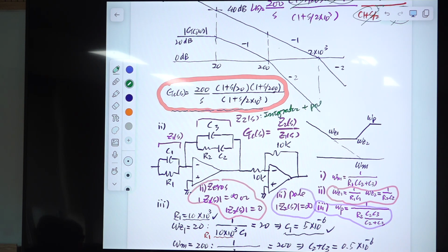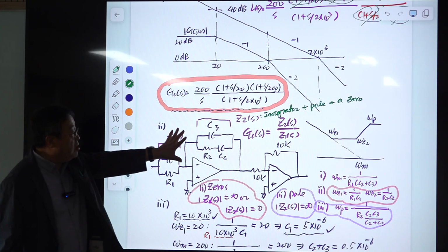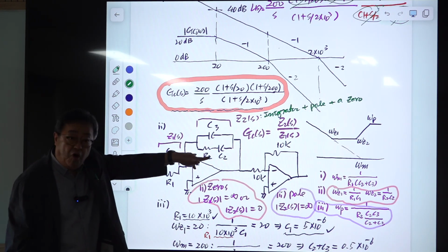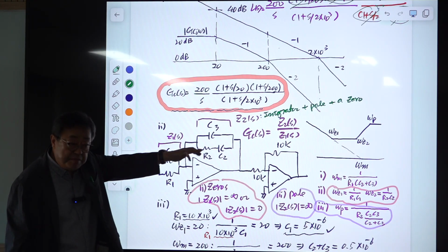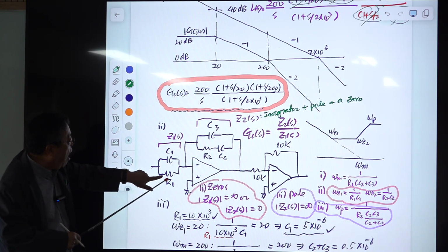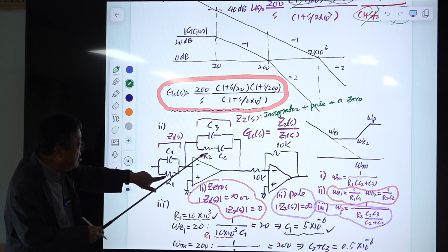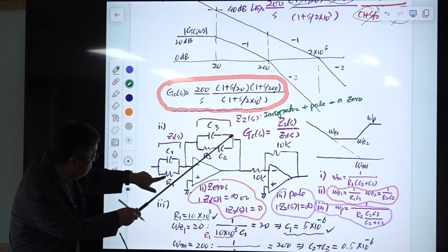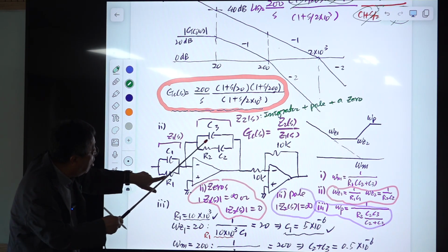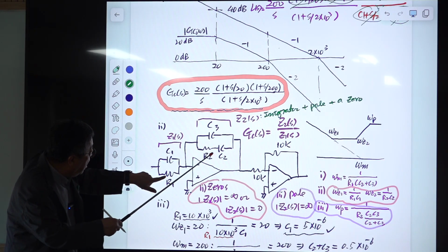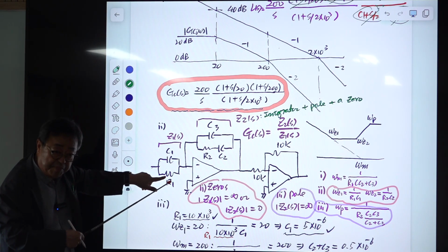One pole, a zero. All right. So the structure of this is determined. You don't want to use 4 elements here. And here, this R is required for what? Integration, right? For the integrator, this is a DC path of infinite impedance, and a DC path for the finite impedance.